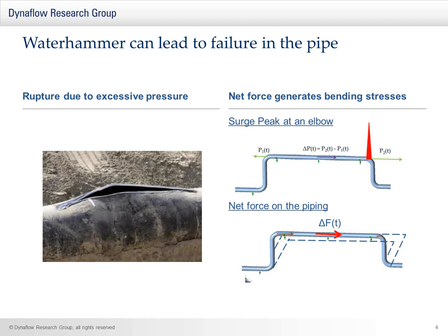If there was an axial stop included, the piping would not necessarily bend, but then there will be a large force on the axial stop located between the bends. And this limit stop may not have been designed for such a large force.